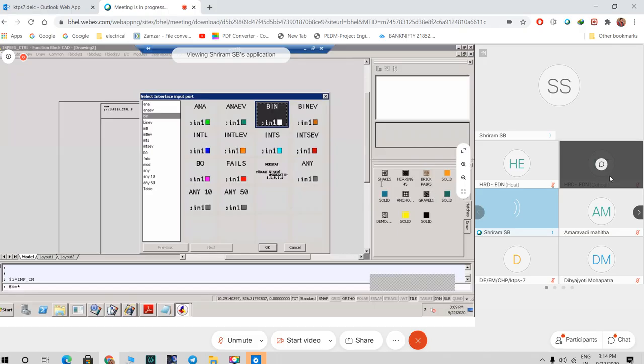Okay, I think someone has asked about the tag 1 speed underscore control that you have entered. Actually this prefix 1 we use for the unit number, because different units will have different prefixes. Suppose you are having 3 units together, then I will be using 1 speed underscore control for unit 1, 2 speed underscore control for unit 2, and 3 speed underscore control for unit 3. So that is the importance of that prefix 1 actually. I will tell you how we convert the software for different units also. So now we can continue with this interface port.